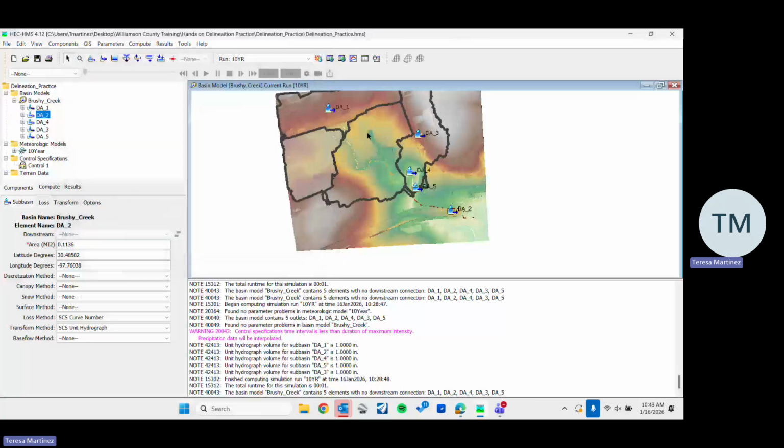And the way you bring it into ORD is that you just attach it as a reference, like a normal DGN reference, and it'll bring up the shape. You may have to apply the scale factor, but it should show up. If it doesn't, sometimes even though it's a shapefile, ORD reads it as an empty shapefile, so it doesn't bring it in. Sometimes it's glitchy like that.